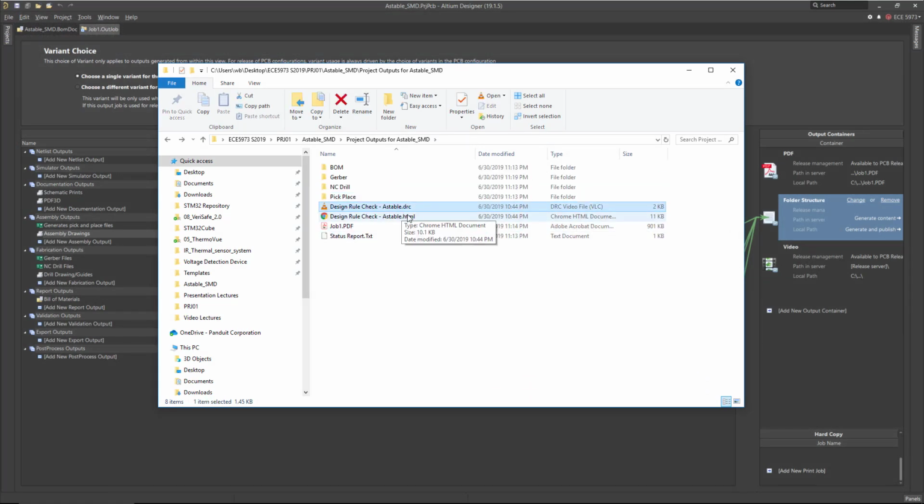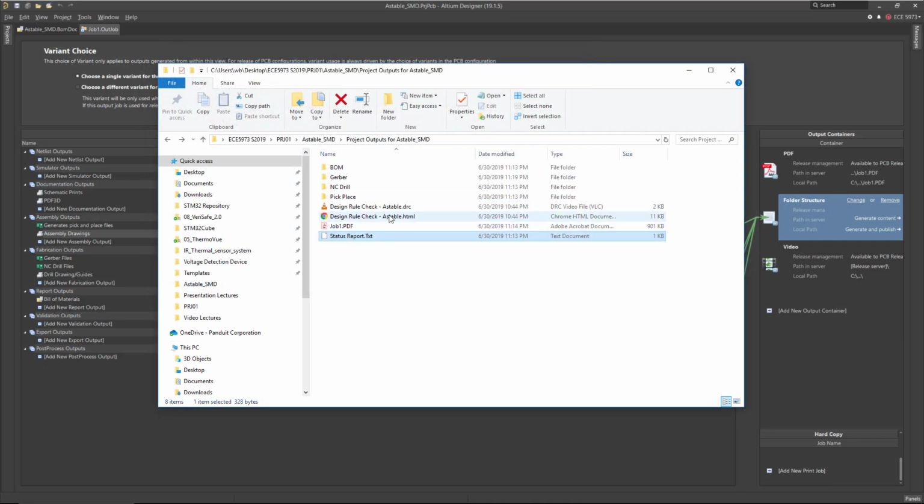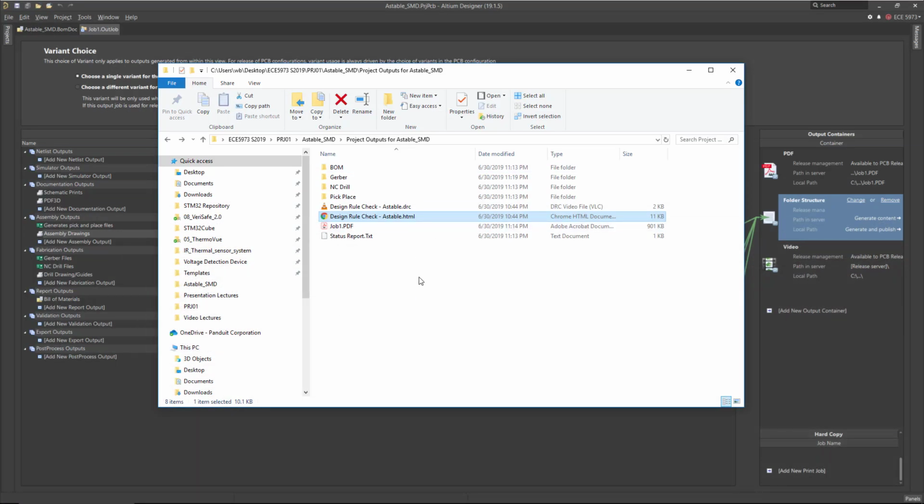Here you have the design rule check errors, and this is a report, just a report, and this is a status report as well. So nothing, file generated and how many files were generated, etc. And this is the file we viewed. This is basically you don't have any errors, you have traceability of this, and you can see if any errors were generated. Just for traceability, you will have it all the time, and it's good to keep it, so you make sure that when you generated the files for this project there were no errors and it's ready to fabricate.